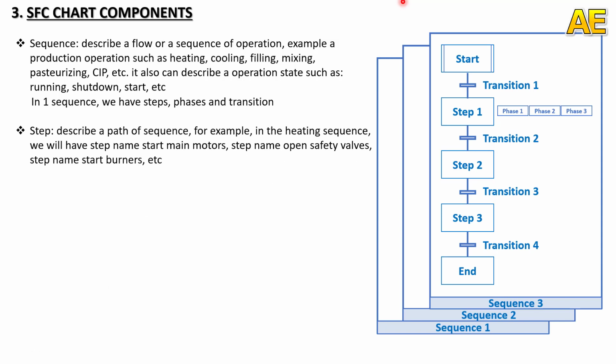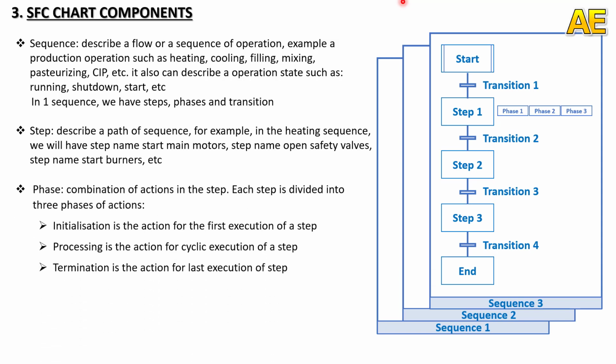Next is a step. A step is described for a part of the sequence. For example, in the heating sequence, we will have the step named Start motor, the step named Open safety valve, and the step named Start burner. That's the example.